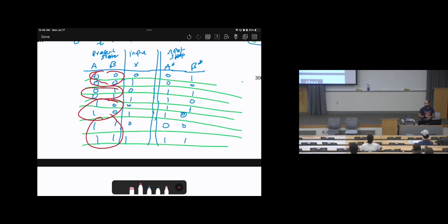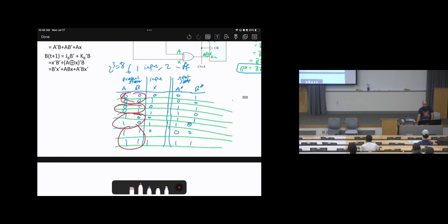There is no outputs. Don't worry about Mealy or Moore's model. If there is any outputs, look at the output. Is this a function of states or not? If it's a function of inputs, we cannot use Moore model. Use only Mealy. If it's only a function of states, then you can use both Mealy or Moore's model. The general model that can be valid for any case is the Mealy model, whether it depends on the state or not.